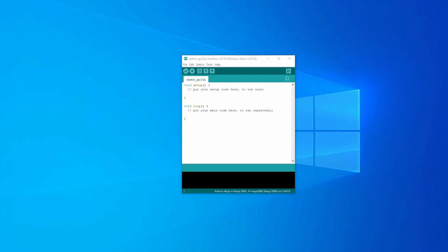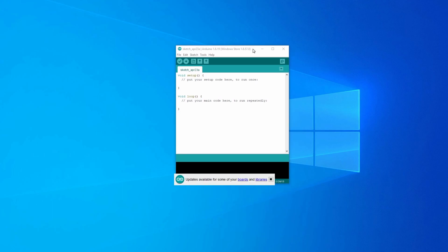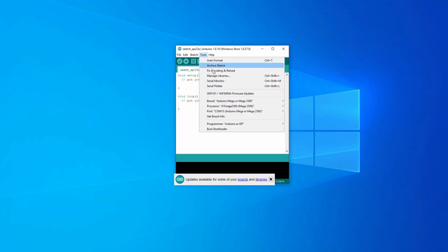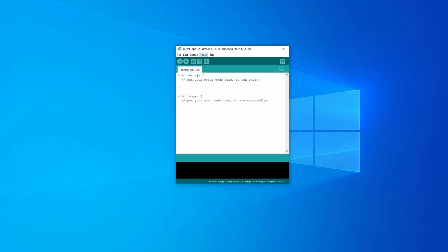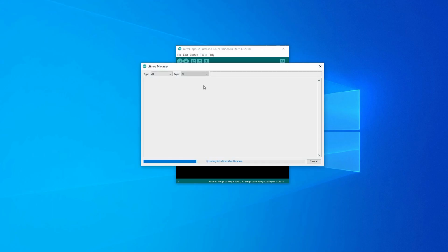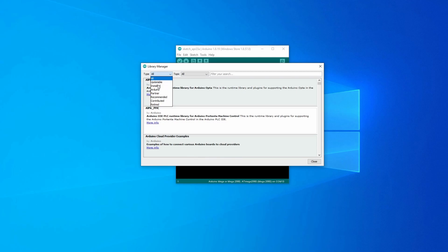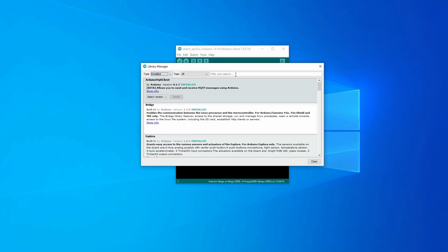I'm going to go right back to the start then and talk through how I got an Arduino that has an Ethernet module attached, working on the Ethernet, talking to that MQTT server. First thing to do is go to libraries, manage libraries, and there we go. And I added the PubSubClient library to my Arduino.